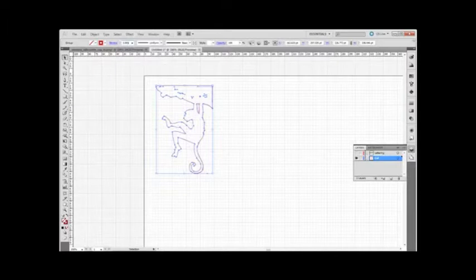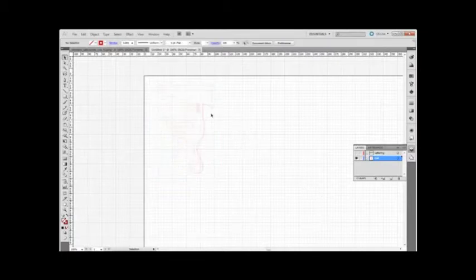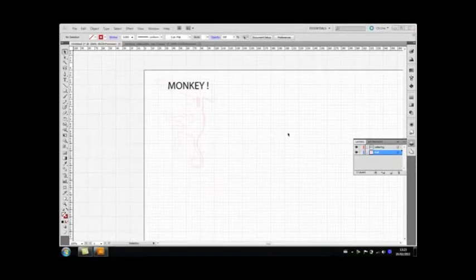Otherwise, the ULS software that we go to across to next won't pick up the cut area. So that's once that's done. Okay, so that's all ready and correct. And now I'm ready to just do the writing as well. So the writing we can leave black because black will just engrave. So that is all fine now. So we're ready to basically go across.